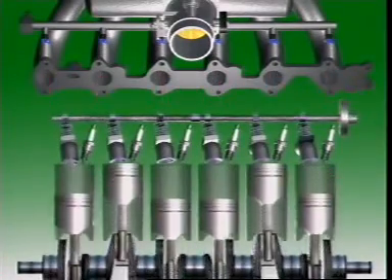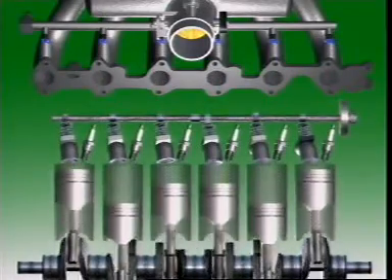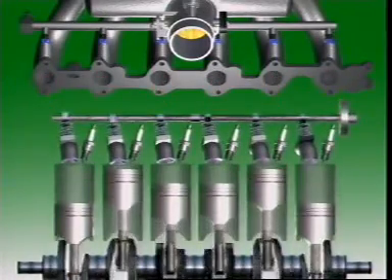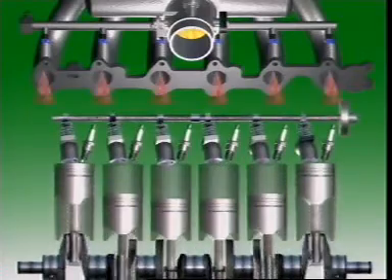The injectors are triggered by the ignition system. So, for a 6-cylinder engine, the control unit triggers the injectors on every third ignition pulse.